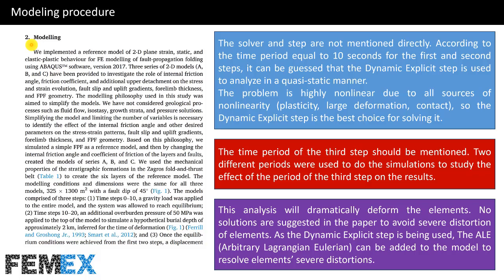According to the time period equal to 10 seconds for the first and second steps, which are mentioned here, it can be guessed that the dynamic explicit step is used to analyze in a quasi-static manner. The problem is highly nonlinear due to all sources of nonlinearity, including plasticity, large deformation, and contact. So the dynamic explicit step is the best choice for solving it.